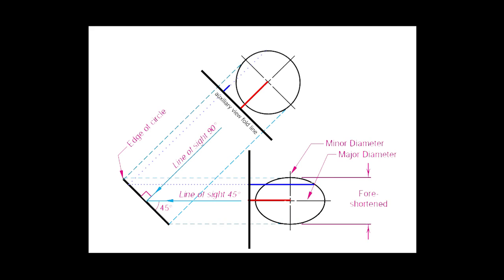Instead, you'll have to use the compass/ruler method to transfer the depth distances from your right side view to your primary auxiliary view. Primary auxiliary view and the right side view are two related views sharing the depth dimension. The same colored lines in both the auxiliary view and the right side view depict the depths of the same feature in both the views.